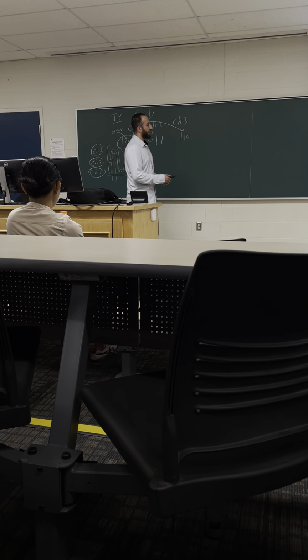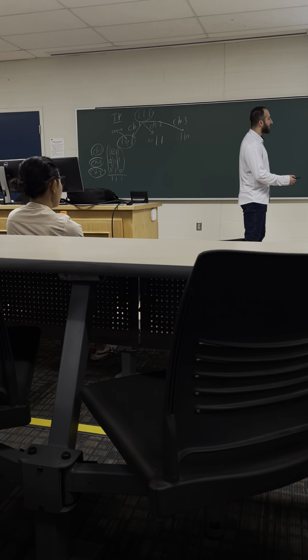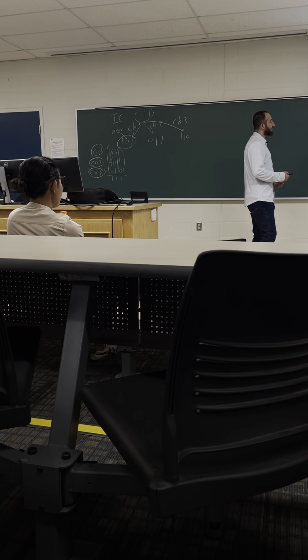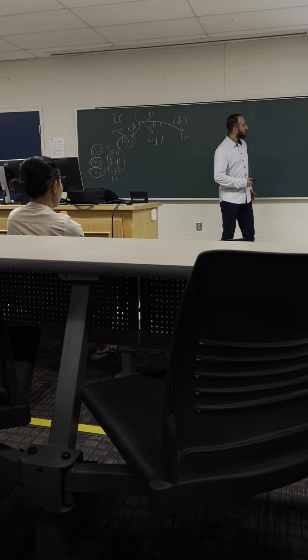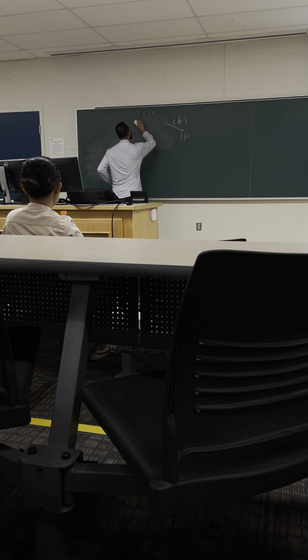So this is what I mentioned here. Consider that you transmit 111 and you receive 3 copies here, and none of them is correct, but after you combine them all together, you will obtain the correct symbol out of the majority vote, okay? So this is actually the basic concept of diversity: repeat over independent channels.